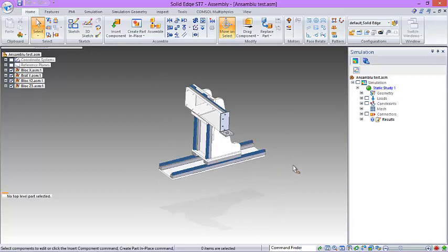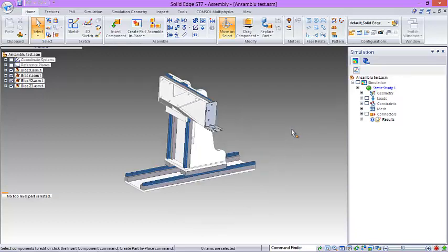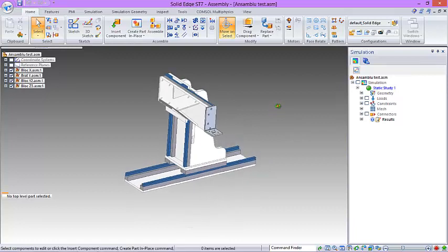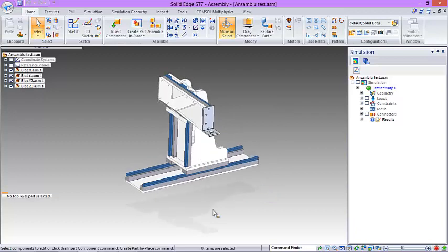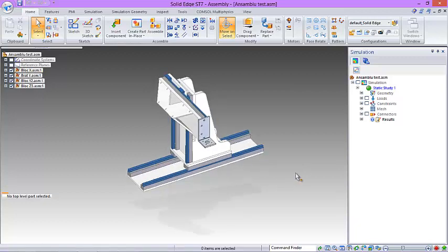Also for a weekend job, because all this has been done in one weekend, I wouldn't say it's much, I wouldn't say it's nothing. I've managed to model, assemble and do an initial stress test of the assembly to make sure that we can achieve a 1 to 10 microns tolerance in an 800 wide, 420 long and 420 tall work environment in which we can apply a 20,000 Newton force.